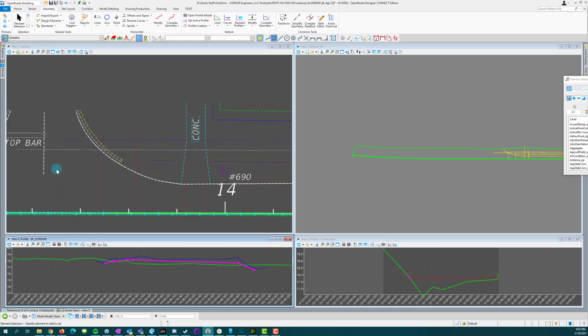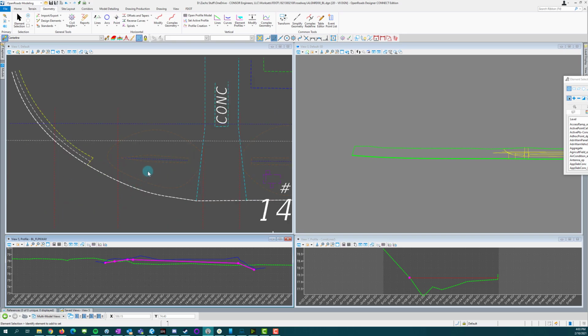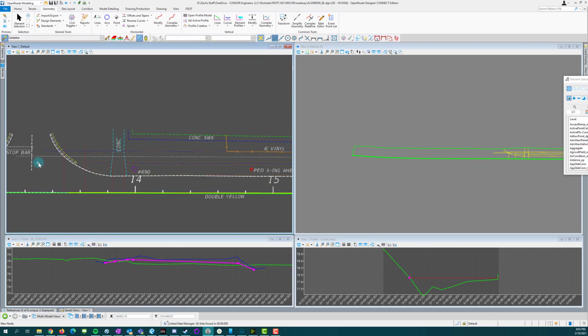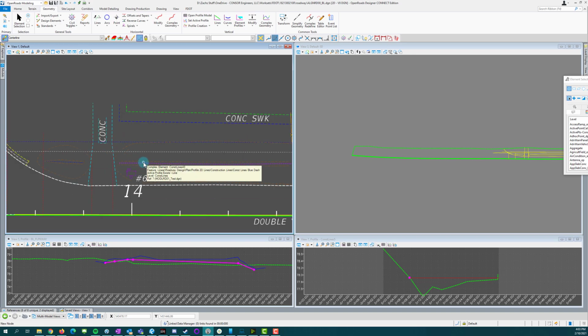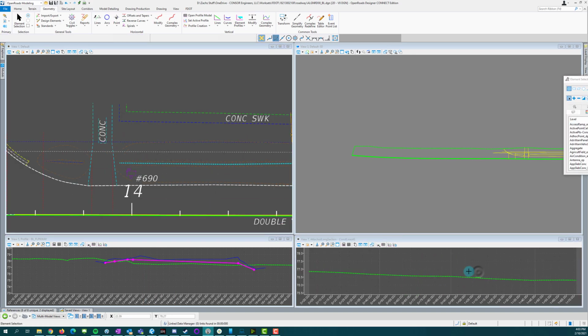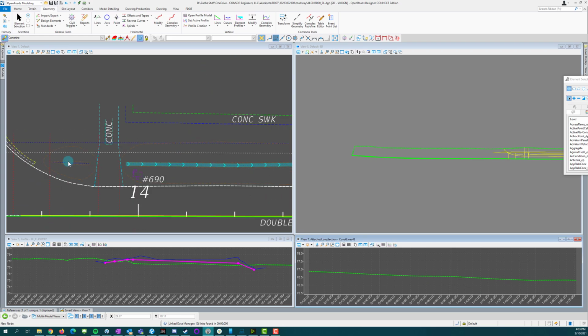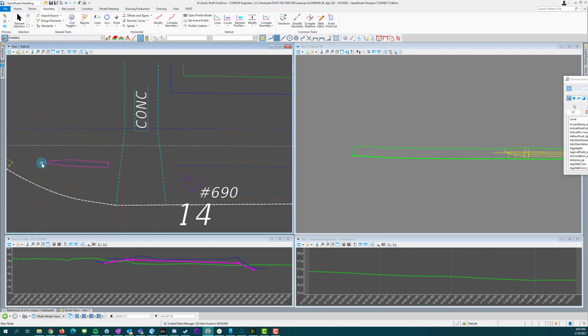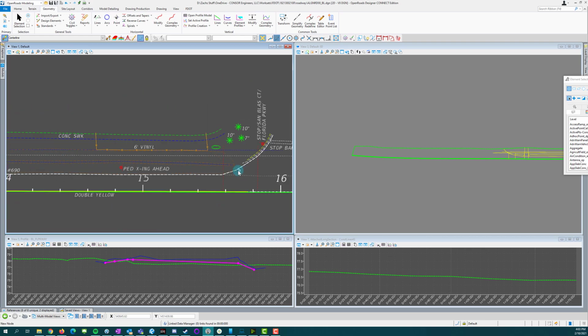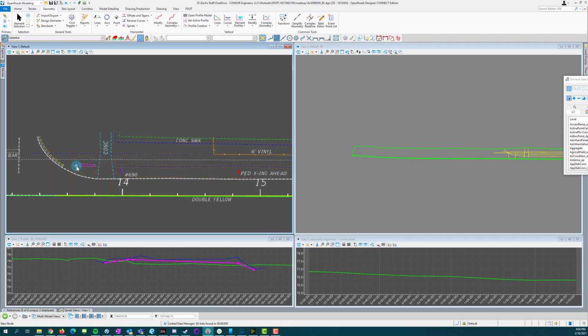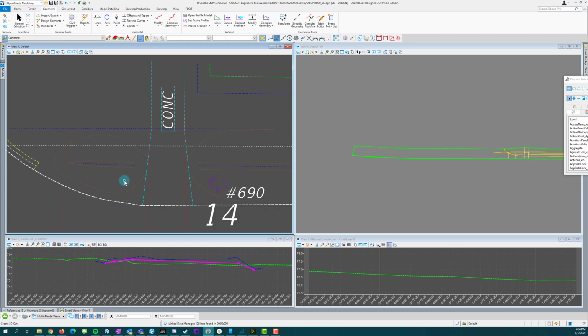The other thing we need to build is the ditch profile. So essentially what I'm going to do is do that in the same fashion as I did before. So we looked at this ditch, and we can look at this ditch profile in here, and it's pretty flat. So I'm going to normalize this, and I'm going to guess that I'm going to have this endpoint, this point here, and this, but I'm going to connect the ditch profile across or underneath this driveway just for clarity. And it may be that I really only need like that point and that point because it's typically flowing from left to right across the screen. So I'm going to pause the video real quick, and we'll come back and we'll have that ditch profile ready to set up.